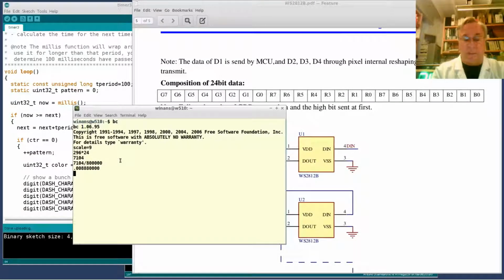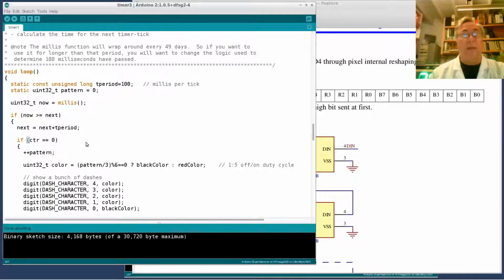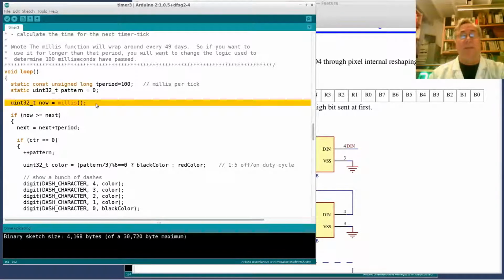Well, what's about 8%? In 1 minute, there's 60 seconds. And if I multiply that by 0.08 to say what's 8% of 60 seconds, it's about 4 seconds. So we've now just figured out where the 4 seconds are going, why I fall behind. There's overwhelming evidence to support the theory that using the Adafruit library is causing me to lose time on my millisecond timer.